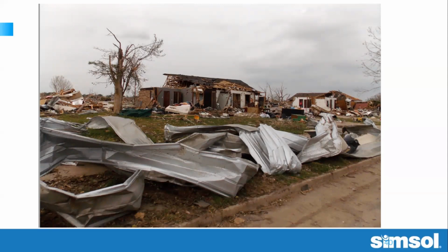Do you find that Simpson clips or hurricane straps are important for the reconstruction, and will probably result in saving the roof? Oh, yes. Yeah, I would say so. I've seen a lot of the newer construction with the tie downs and the clips, that definitely helped. A lot of the newer roofs with the secondary waterproofing membrane underneath cut down on a lot of water damage inside. But you can definitely tell the houses that were older, that hadn't been retrofitted or hadn't been built to today's codes, suffered quite a bit.